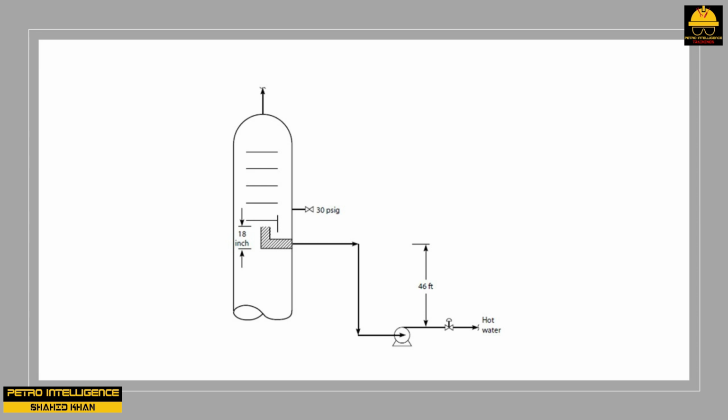But this is still a lot more available NPSH than the 14 feet of required NPSH needed to pump 110 GPM. If I now open the discharge flow control valve sufficient to increase the flow from 100 to 110 GPM, or by 10%, this will increase the frictional loss in the suction piping by about 21%, or about 0.5 psi, since delta P varies with the square of flow. But this is not what I observe. The suction pressure in the picture slips from 47 to 36 psig, at which point the pump begins to cavitate. What is happening?